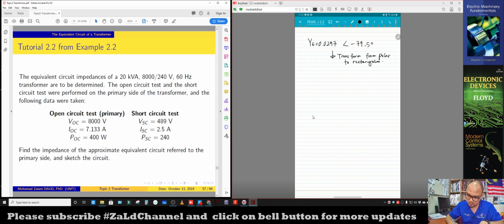So once we transform it to rectangular form, we actually get another value of admittance, 0.00693 minus J 0.02888. So this is basically the conductance and susceptance. This is the conductance, and this is the susceptance.